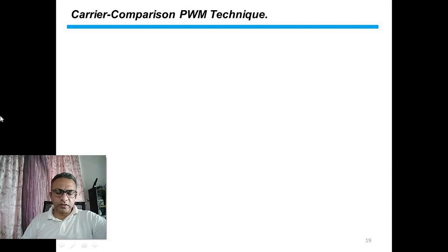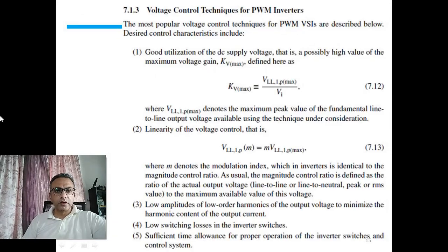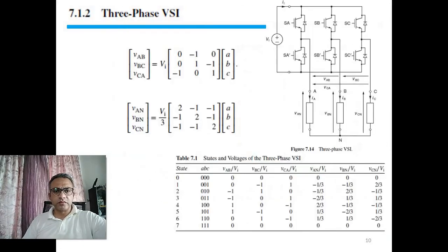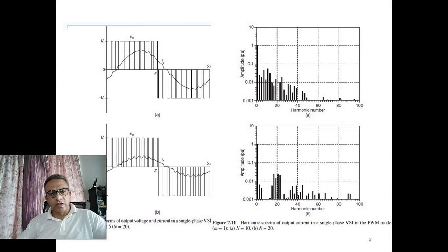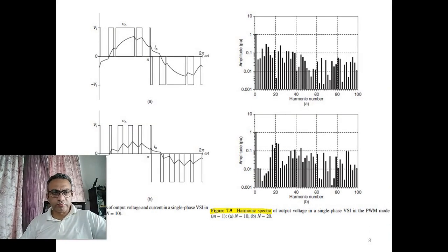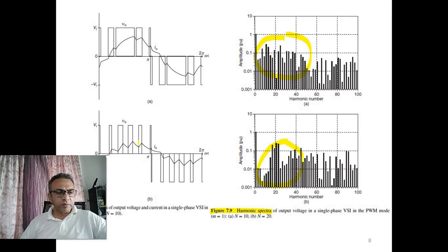If we look back at the slides that we covered earlier, in the PWM case we always have a certain number of low order harmonics, and we can reduce them by controlling the pulses.